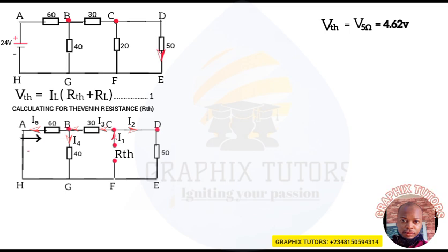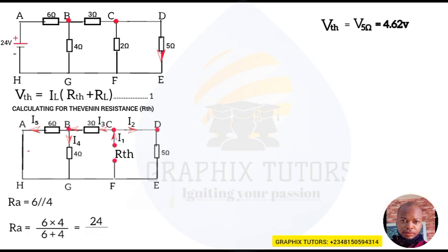So because we're taking our point of reference in between them here, what do you notice? I5 is flowing through 6 ohm, I4 is flowing through 4 ohms, making what? 6 and 4 in parallel, because two different currents are flowing through them. Now I will use R of A. You know the reason why I'm using it? Because that is not the total resistance in that circuit. So R of A is giving us what? 6 parallel 4. And 6 parallel 4 means 6 times 4 divided by 6 plus 4, which will give us 24 all over 10.